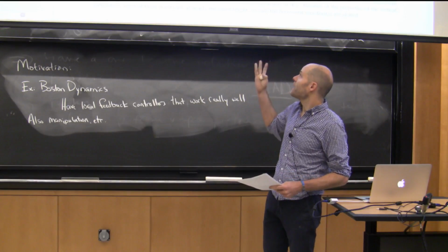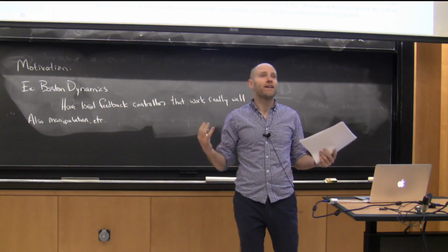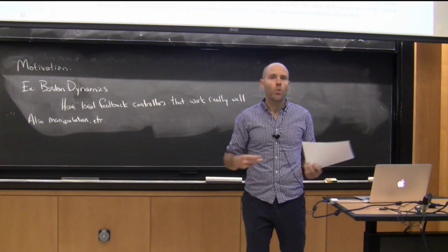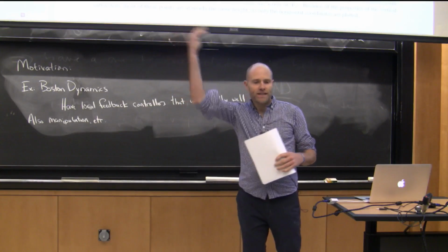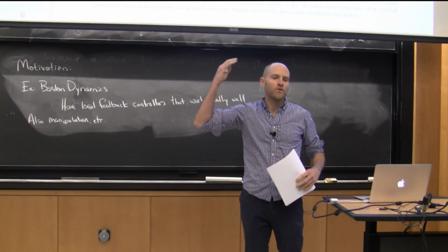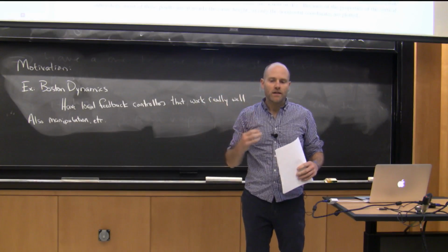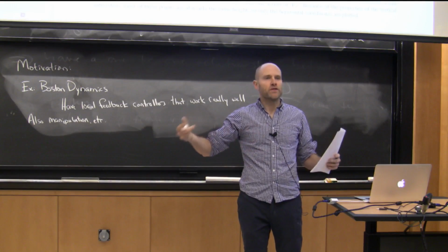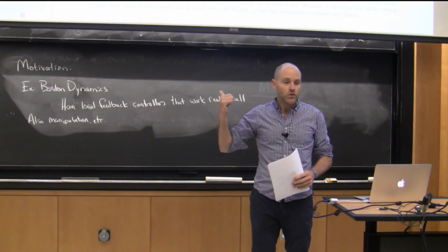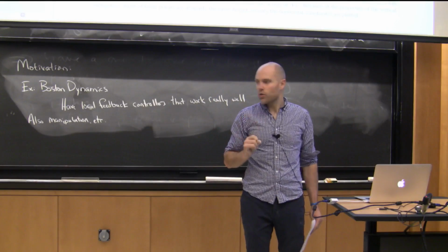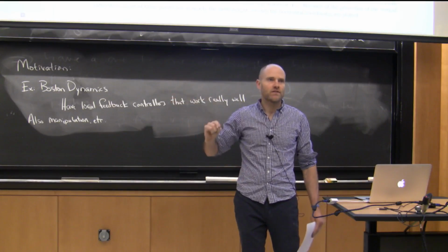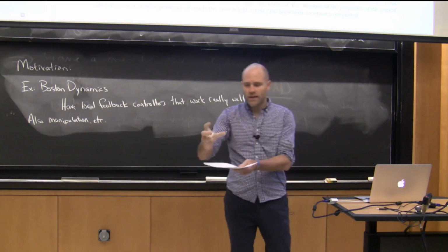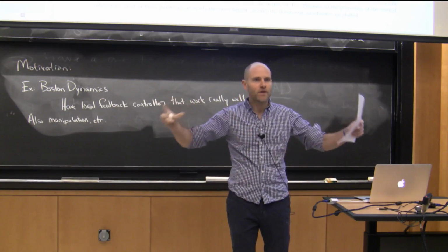So they didn't really have the motion planning ideas, like the RRT type ideas of filling the space, weren't available then, right? So they weren't able to give us a powerful set of tools for saying, okay, if you have a bunch of controllers that are parameterized, how do you then reliably fill the space with those controllers? What they could do would be, I'm going to just instantiate this controller with k equals 5, k equals 6, k equals 7. And that comes up with some controller which has some region of attraction, hard-earned experiments, that has something like this. And if I do that enough, maybe I've covered the space.